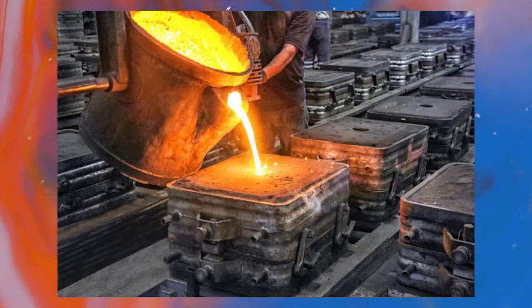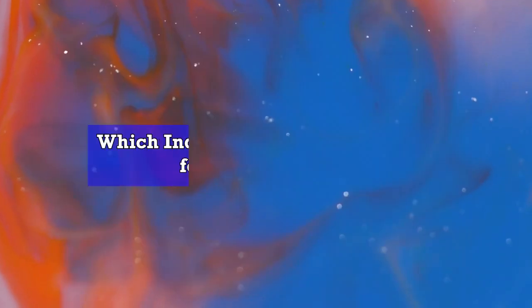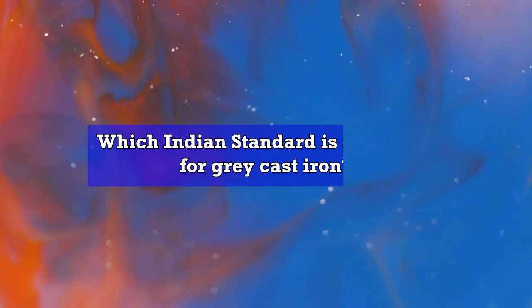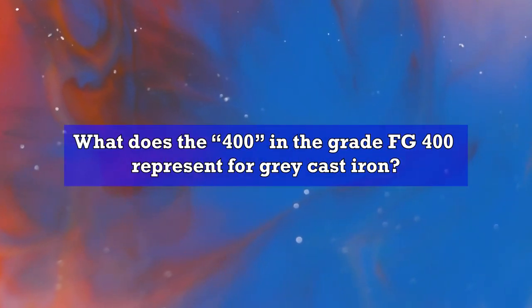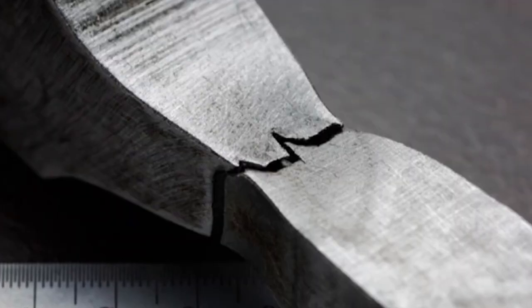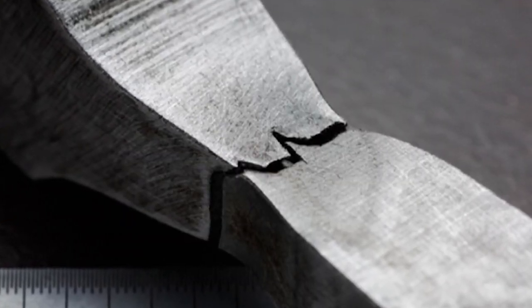Let's dive into some interesting facts and questions about the product you have just learned. First up, here's an easy one. Which Indian standard is available for the grey cast iron? That is IS 210. Now, let's get a little more specific. What does 400 in the grade FG 400 represent for grey cast iron? It represents the minimum tensile strength for the grade FG 400 should be 400 megapascal.